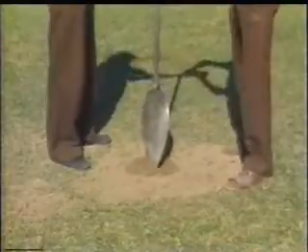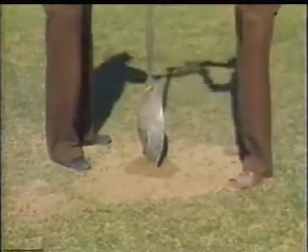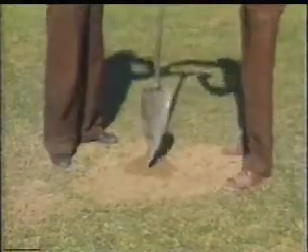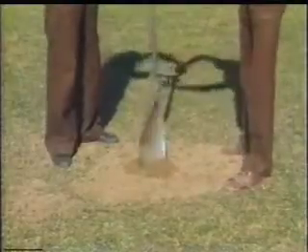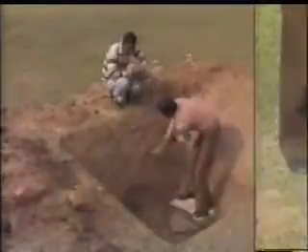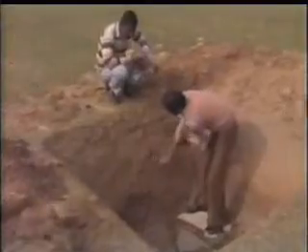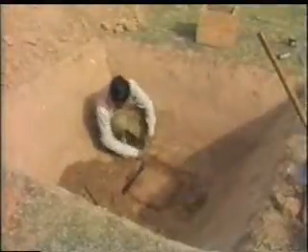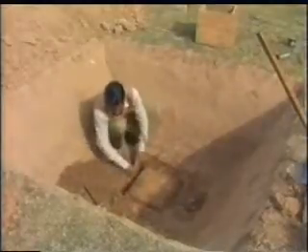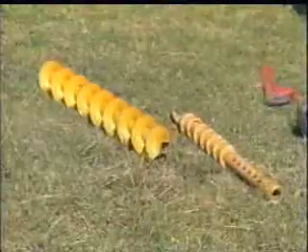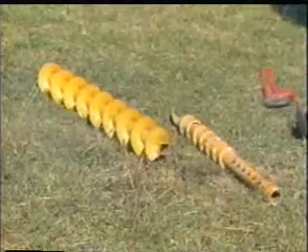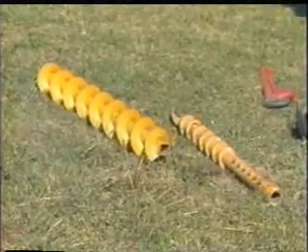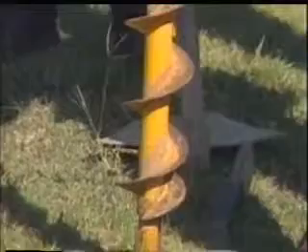Methods explained so far like auger boring, tube sampling, pit sampling, etc. are used for shallow or moderate depths. These are suitable for design of isolated footings, combined footing and raft foundation of smaller dimensions.